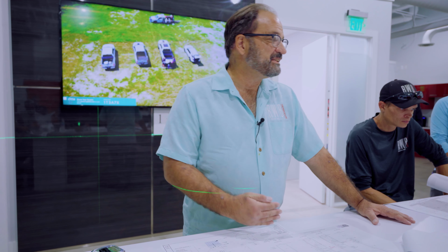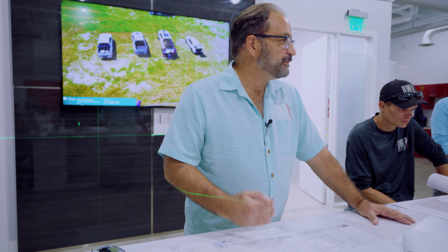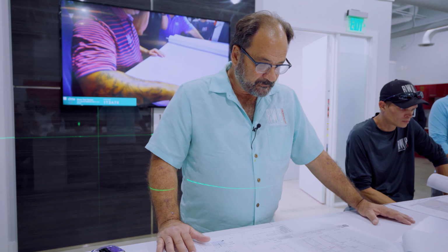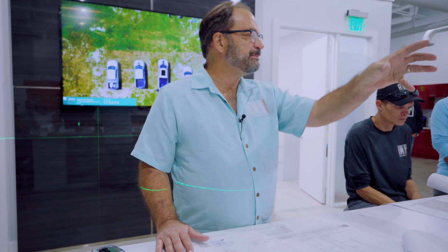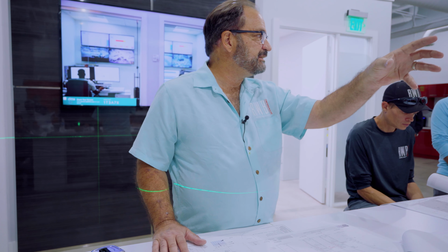Again, it's critical path. When you're doing something, you have to understand, and this goes back to the same theme, why you're doing it. What's the next step? If you're just putting an outlet there, you have to think in your head, all right, I'm putting an outlet there. Once the cabinet's in, how's he going to get into it? Is it going to be accessible? Does it work in relationship to real life?